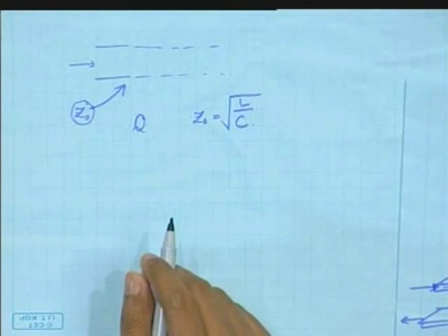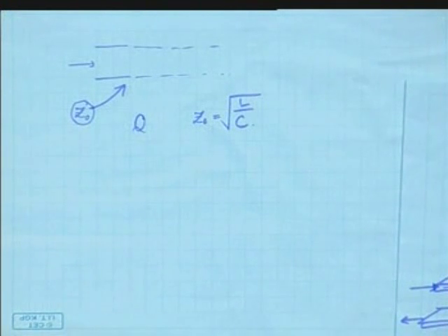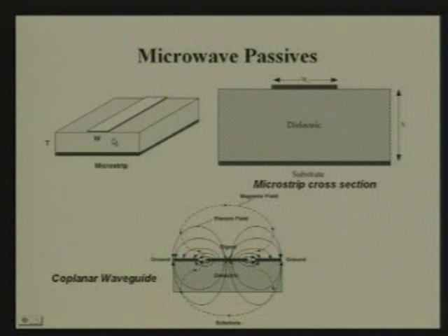Okay. Now there are different microwave structures available. This is the microstrip line, where this is the signal conductor, the topmost metal layer, and there is a bottom ground layer which acts as the return path. And in between there is the dielectric. Suppose these are two metal layers, M6 and M5.